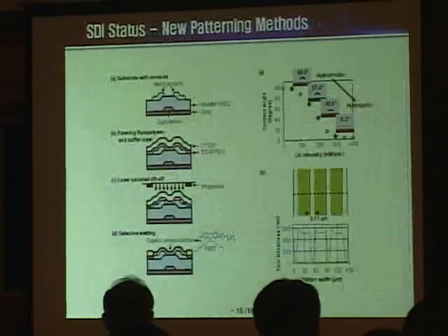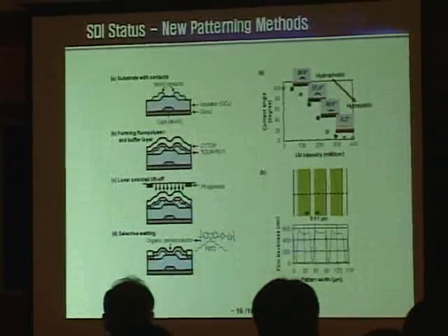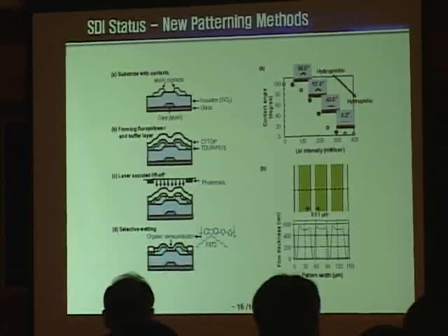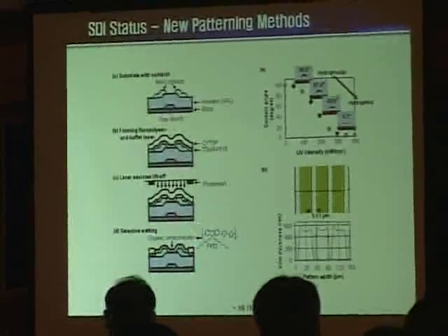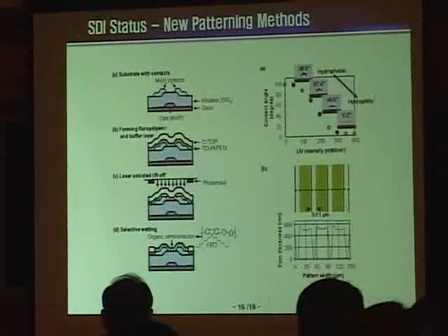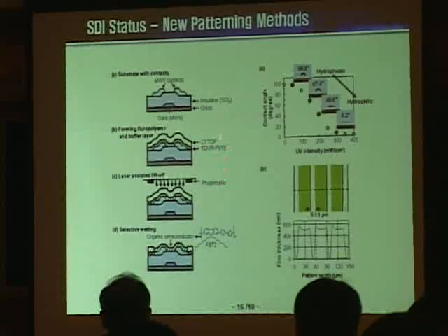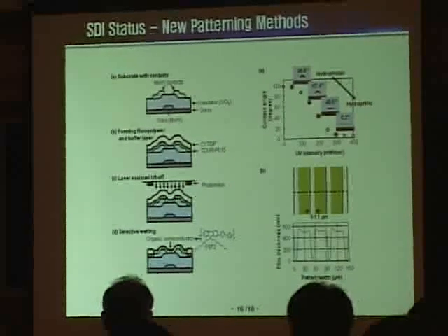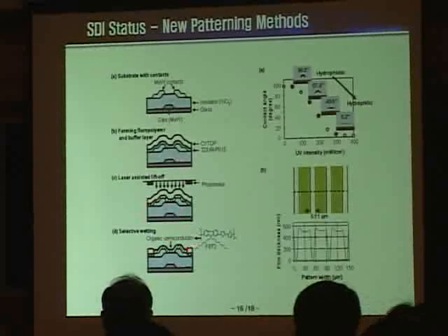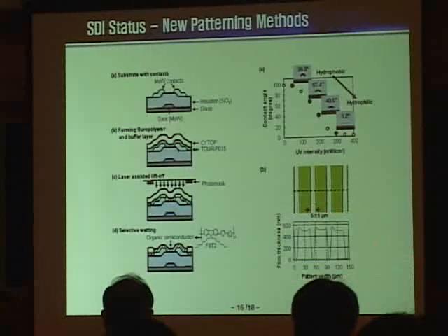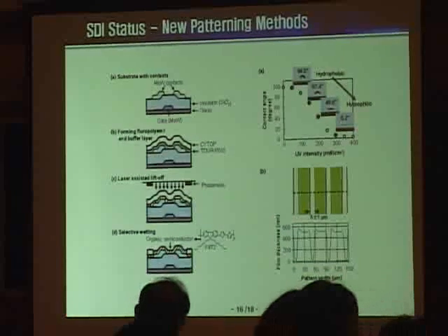Next slide, please. As a self-aligned patterning method, we developed a laser-assisted patterning method like this. The key point is the wettability control of the channel area in this case. In other words, we eliminated the Cytop polymer, which is fully fluorinated and repellent to all kinds of solutions. Then we just spin cast the organic semiconductor to cover the channel area like this. This profile shows you the groove after the laser-assisted liftoff.